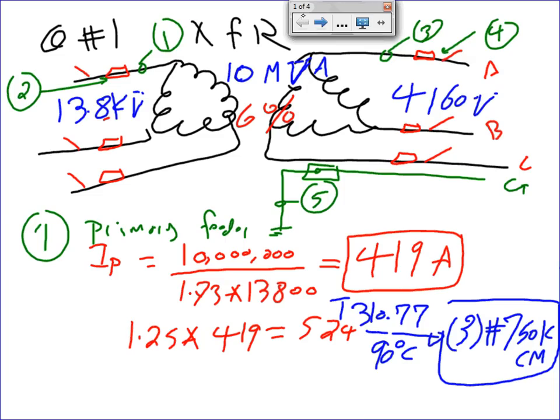The second ground fault, on a different phase, not on the same phase, will bring you down. If C and G are tied together, no problem. If B and G are tied together, that's no problem. But if B and C both go to ground, you've got a line-to-line short circuit. If you bring C to G, and tie B to G, then C and B are tied together, a two-phase short circuit. So that will bring you down.